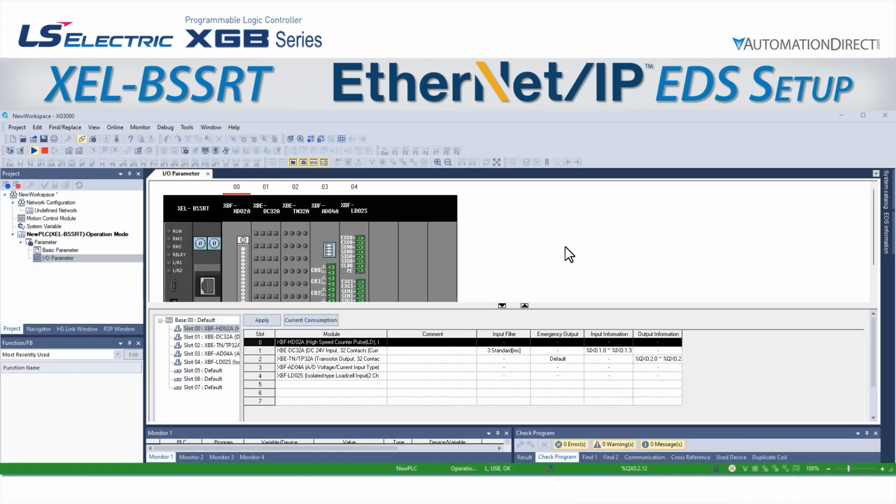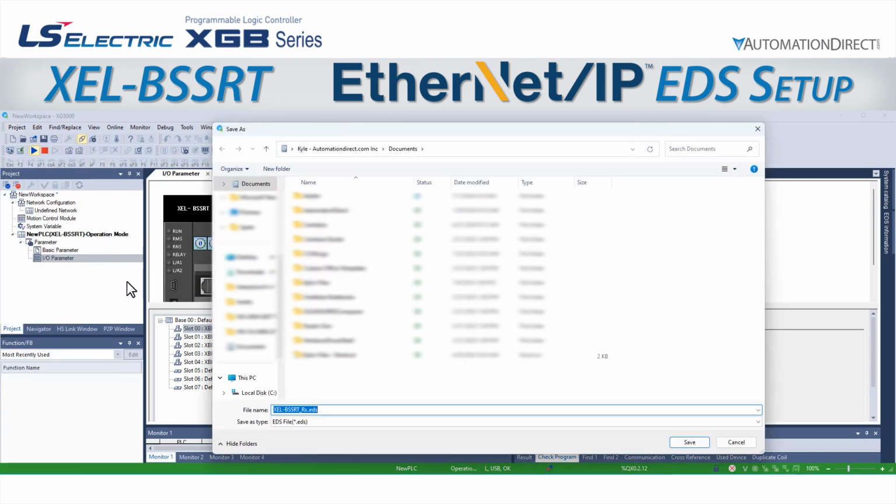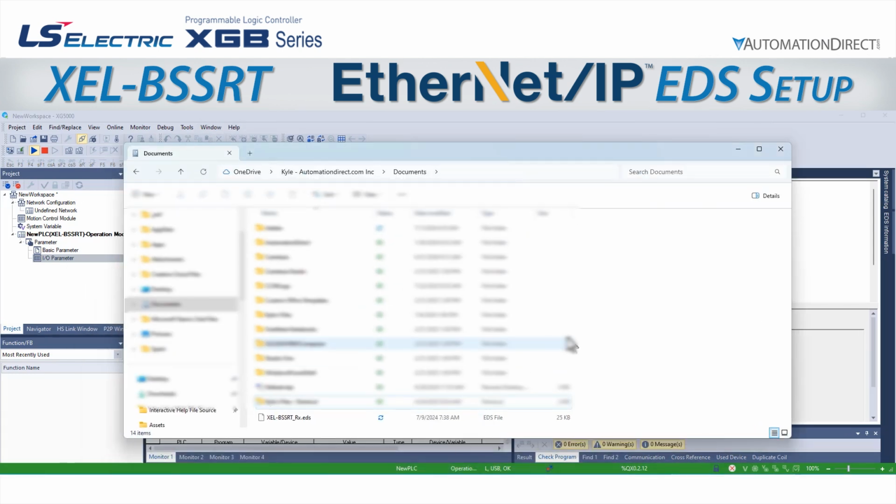Let's start in XG5000. This is the BSSRT project we created in our setup video. We are connected to the bus coupler and are in run mode. To generate an EDS file, we simply go to Project, Export Ethernet IP EDS File. This will open the Save As window, and we can select a place to save the EDS. We will save it in the Documents folder, and we will keep the default name of XEL-BSSRT_RX. Once we click Save, we can go to Windows Explorer and see our EDS file in the Documents folder. Great! We are now ready to add it to our Productivity PLC project.